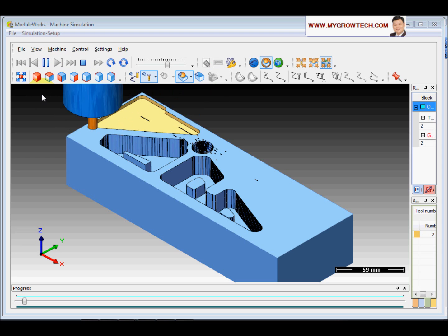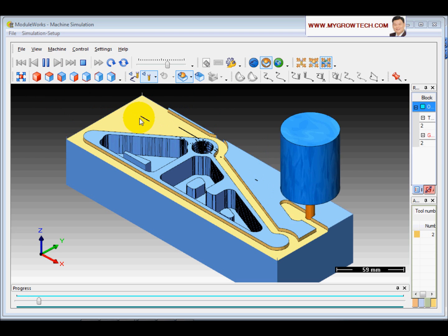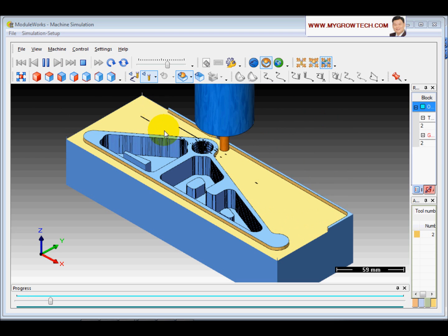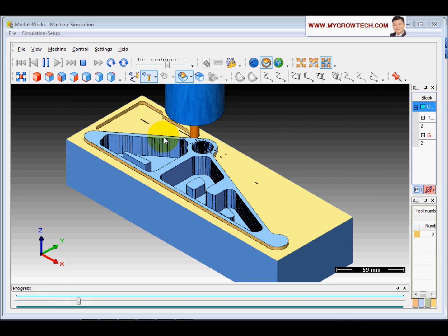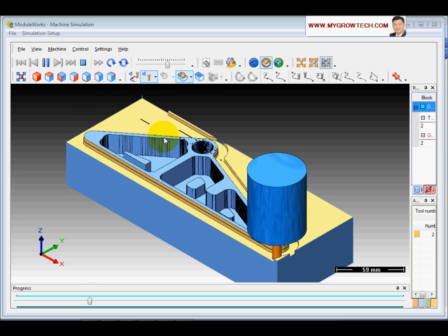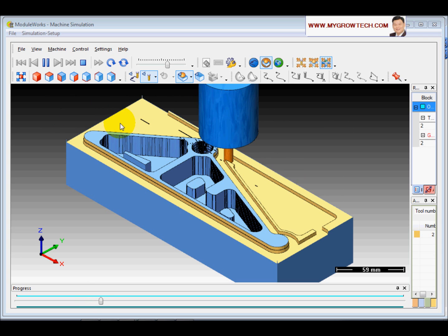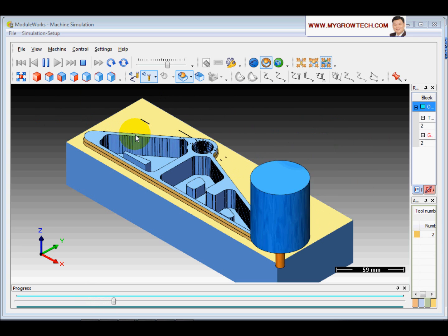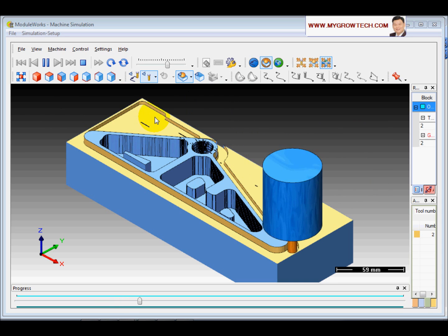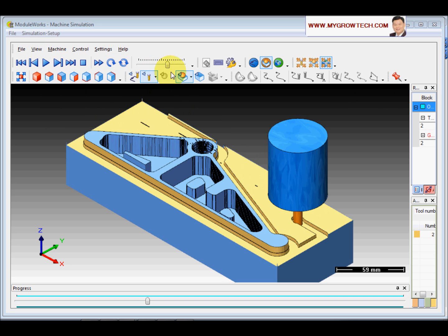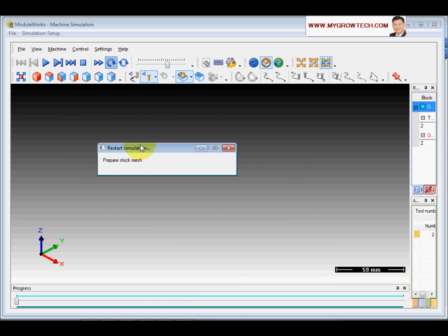As you can see, if you select the two contours, the stock and path contour, as a path contour, Cimatron will assume this is a closed pocket, and the entry will be a ramp entry, and it will cut from the inside out. Let me reset this.